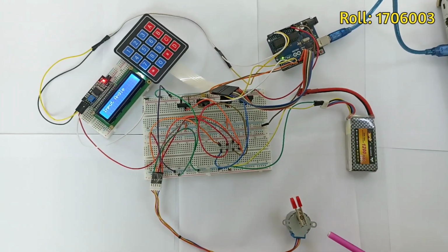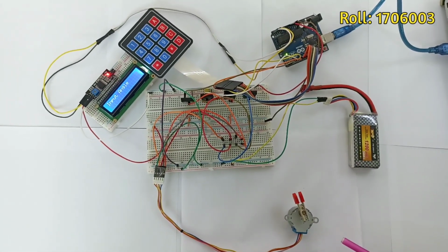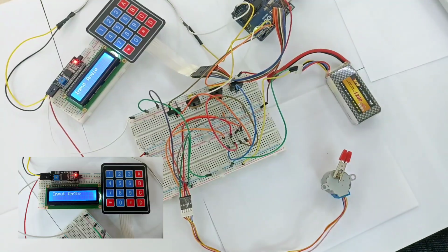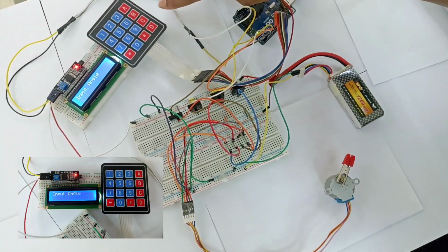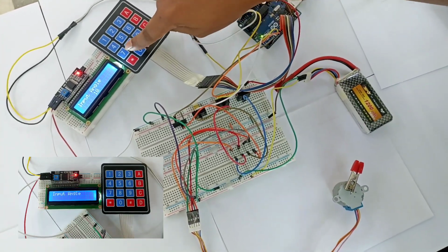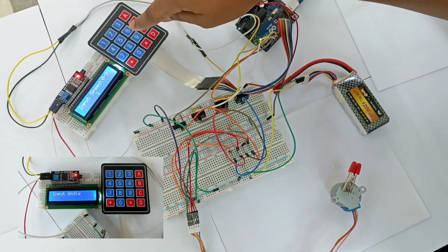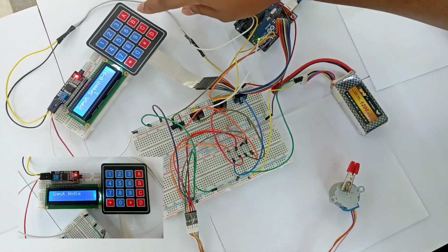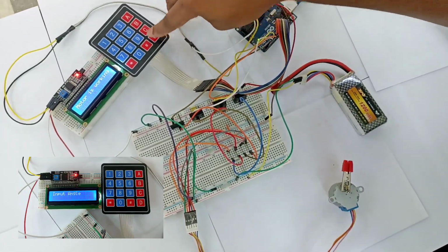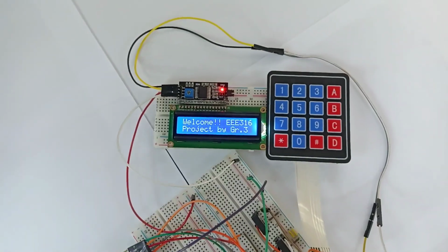The stepper motor has a step angle of 0.1758 degrees and takes a total of 2048 steps to complete a revolution. Now this is our user interface for driving the motor. If I give input angle of 180 degrees and select the rotation counterclockwise and give an input speed, the speed is a relative scale of 0 to 9. 9 is the fastest speed. So if I select 9, you can see the motor is rotating in a counterclockwise rotation.